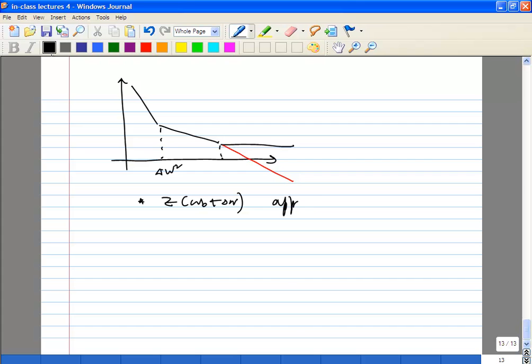But probably much before that, what you'll hit is, you'll end up having to use some buffers to drive your external circuits. Okay, those buffers will end up having a thermal noise floor at the output. So it will be limited by that. Okay.